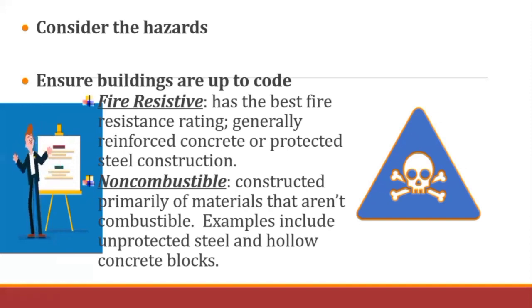you design, or when designing a building, make sure that you also consult with the Bureau of Fire Protection. Or while constructing, you also need to call the attention or make a request to the office of the Bureau of Fire Protection to inspect the building being constructed, so they may give recommendations on the safest design of the building.